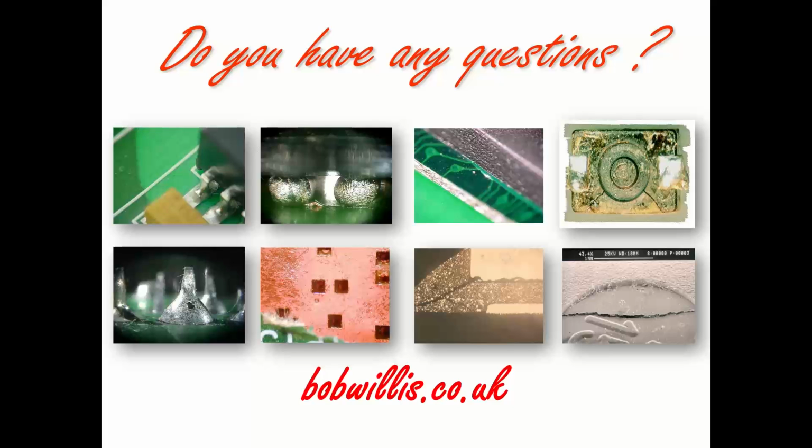So a lot of the simpler, smaller parts, no, but some of the more sophisticated LEDs and power LEDs we have today, potentially yes. Sometimes you have plastic moldings over the LED, which can expand and cause separation of the bond wires. I have seen that, and I have examined that for companies. If we look at SOICs, today that would be very unusual. Mechanically, they're very robust. But when we look at area array packages, small flip chip devices, anything that's got bulk plastic or a combination of plastic and fiberglass, yes.